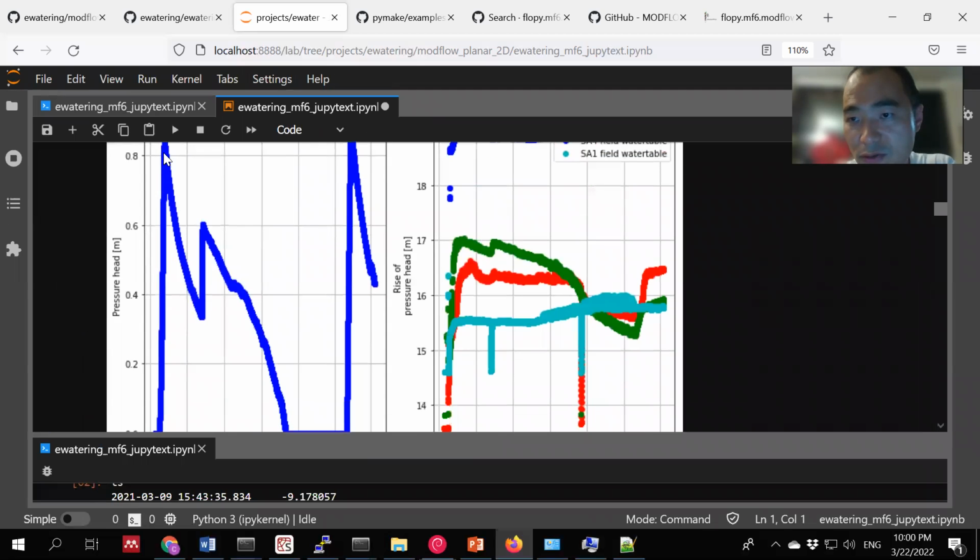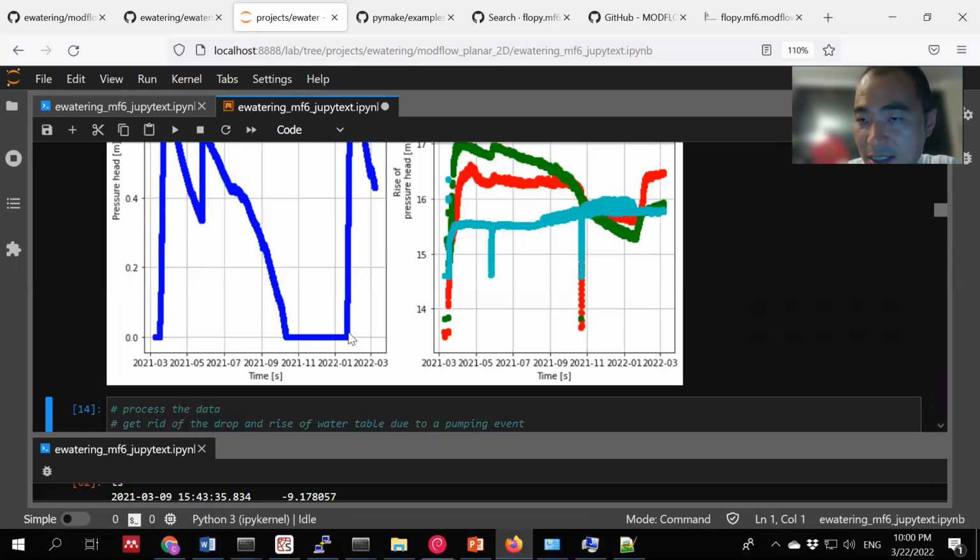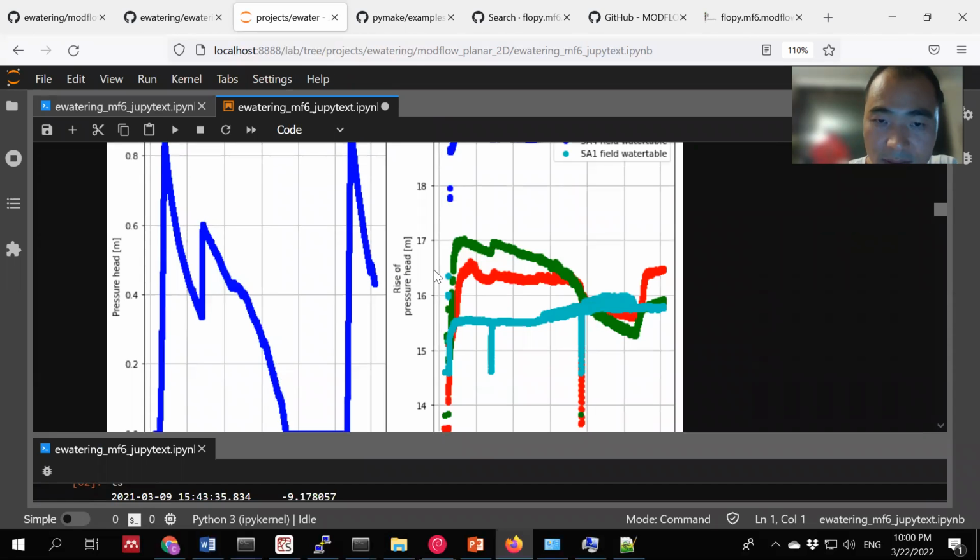So rise because of pumping, draw down because of infiltration and evaporation, pumping again, draw down, surface gets completely depleted, rise again and draw down. And if it's rising, groundwater table rises almost immediately, which is due to recharge, but it draws down very quickly as well because recharge is reduced and also water dissipates in all directions. Get another top up, rise a little bit and fall down to the original value. And then it rises again because we top it up again. So that's just the raw data.